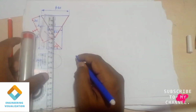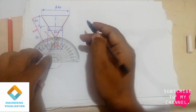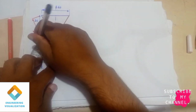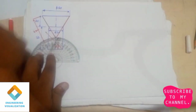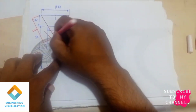Diameter 30. In order to divide into 8 equal parts, we will be using an angle of 45 degrees. Using the protractor, we can do it. Mark angles 45 degrees, 90 and 135. I think you are not able to see the points properly, so I'll be using the sketch pen so that you can get the exact points. 45 degrees here, guys. 45 degrees, 90, 135 and 180.